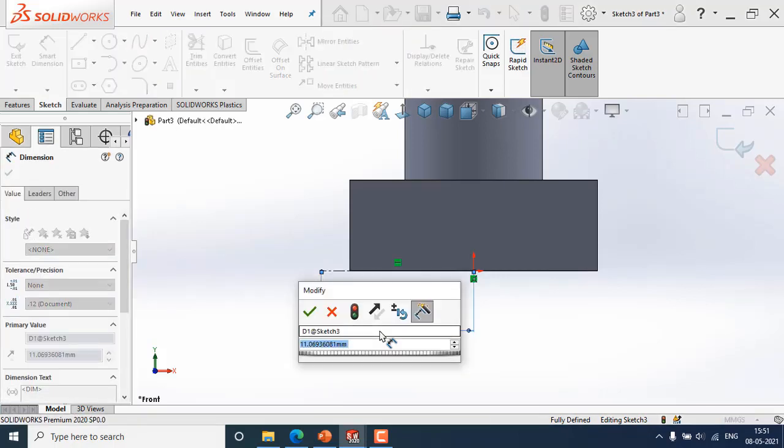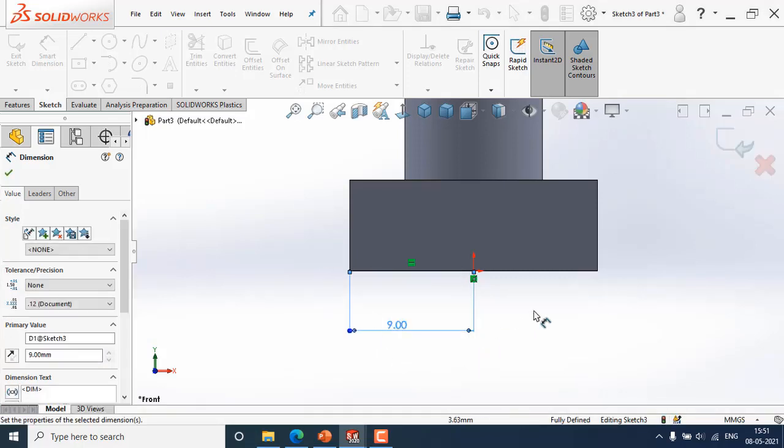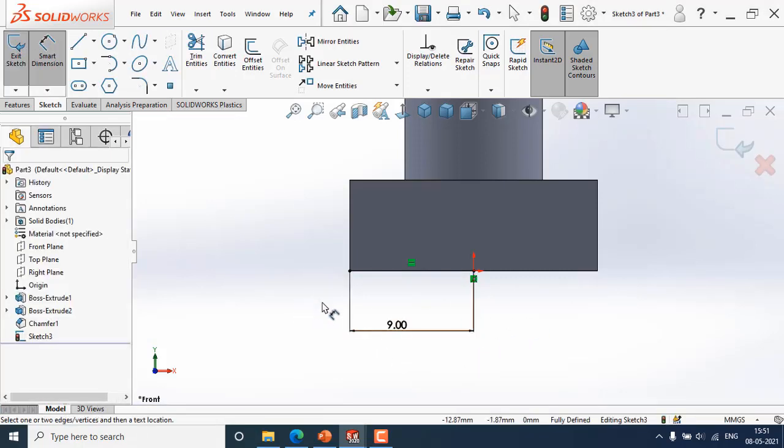1.5 is the diameter, it is the square. The diameter is M10. That should be the reference D. D we know it is 10. So 1.5 D means 15. 15 plus 3. This overall length, we are doing half of the 10, so it should be 9.5. From there, draw a chamfer line.